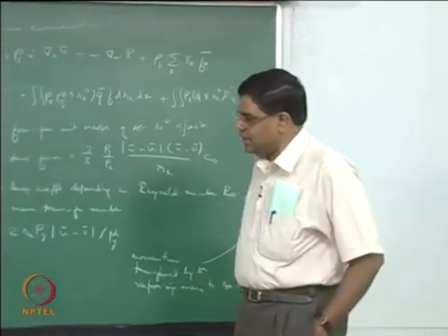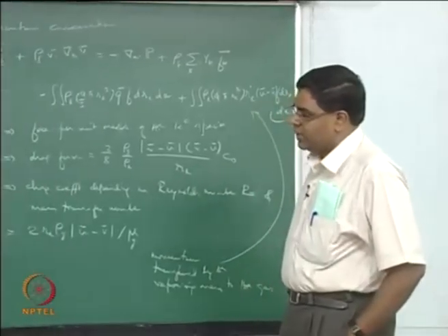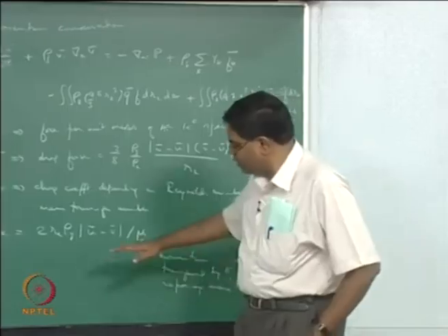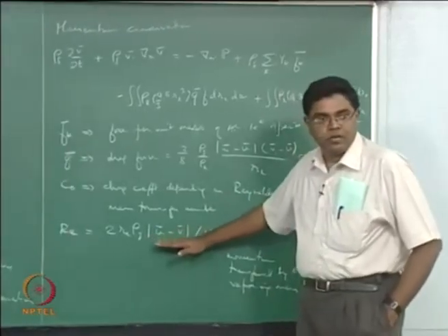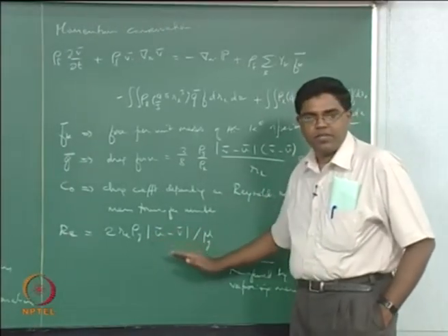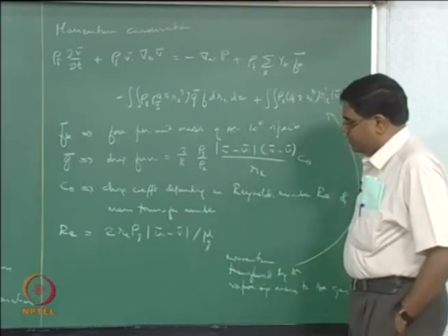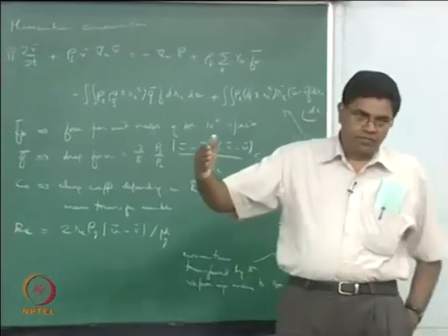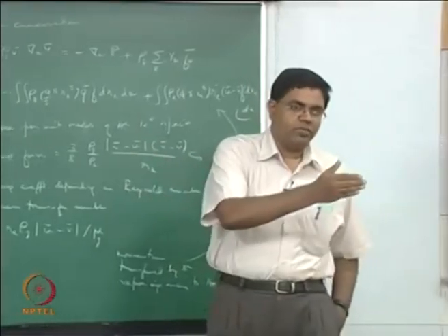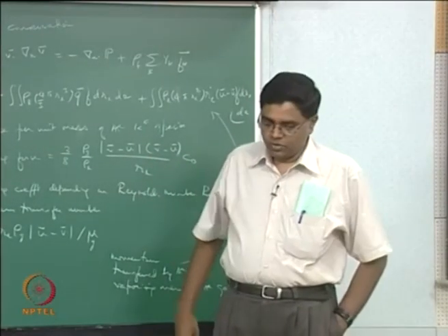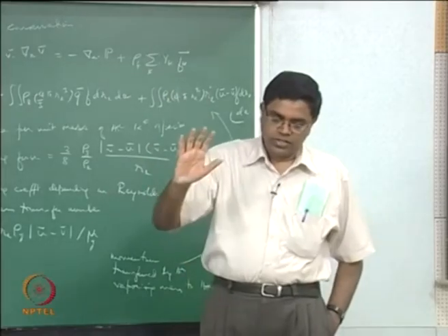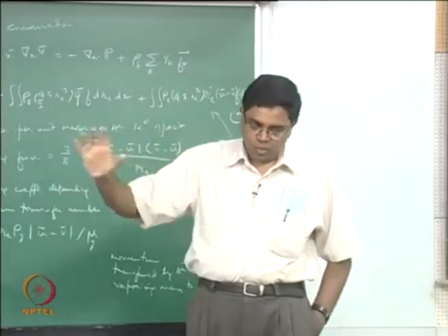So typically what happens when you now have a locally high Reynolds number situation based on the relative velocity between the gas and the droplet velocity, you could now have a wake that is shedding behind the droplet. Okay. So you now have a overall turbulent field into which now the droplet is actually moving